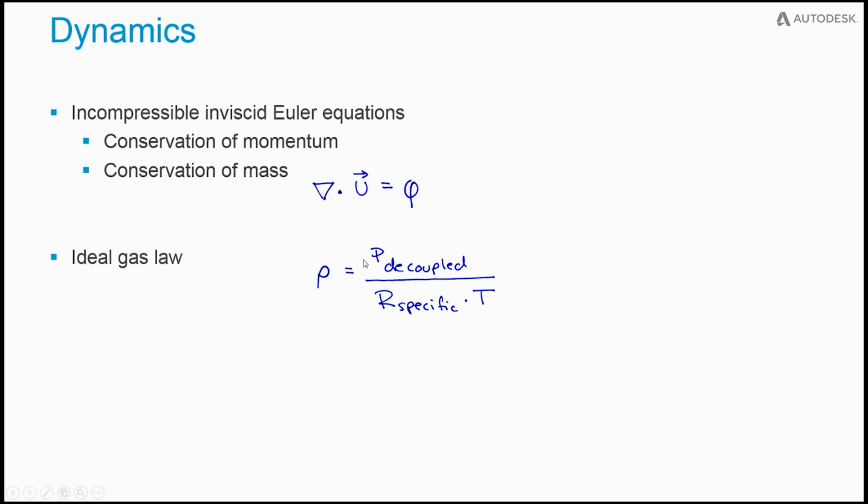So we decouple the density and the pressure here, and in our case we use a constant pressure when we evaluate the mass density, and we just use the pressure of 1 atmosphere. And that is justified if you have simulations that are not contained but can freely expand. And you could also imagine using other types of decoupled pressures where they depend on the height into the atmosphere, for example, which would mean that you could use it to model things like clouds or nuclear explosions.